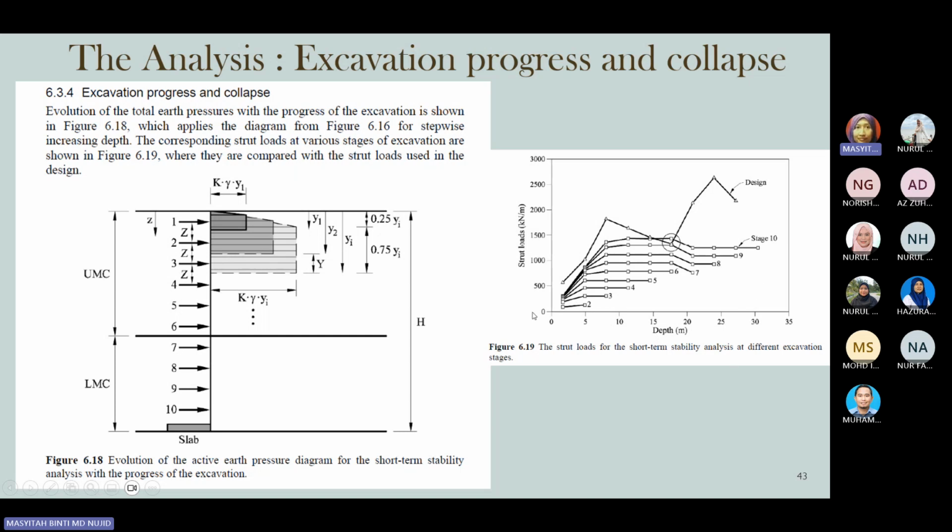Even if Z is equal for strut 1 and strut 2, the depth applied changes differently, but it can be given as linear. When you increase the depth of the penetration, or the excavation depth, at the different stages, it also increases the strut loads.